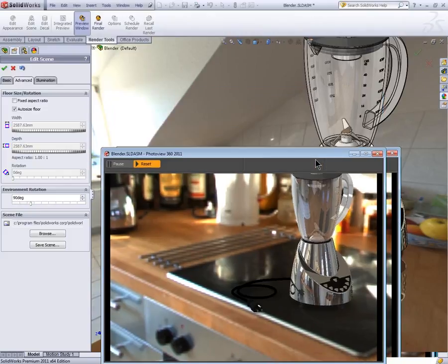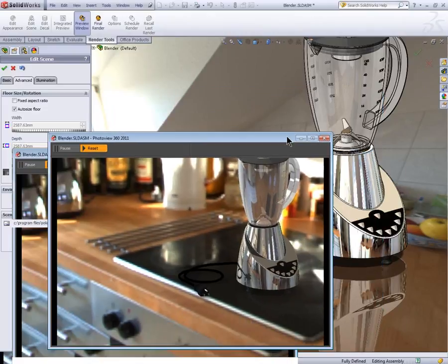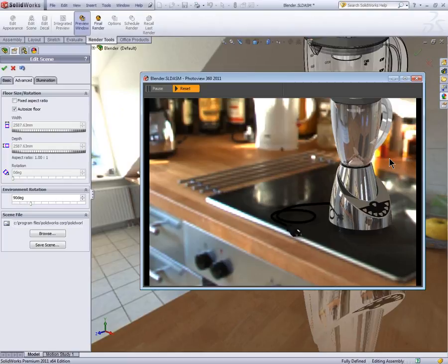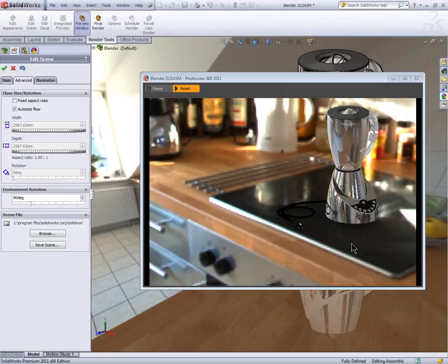Alright, so now it may not look right in the SOLIDWORKS environment, and again, this has a little bit to do with your PhotoView render size versus what you're actually seeing on the screen. So if you're doing like a 16:9 render size versus what you're physically viewing in SOLIDWORKS, it's going to throw that aspect ratio off a little bit. So that's why we're distorted. If you had your PhotoView settings set to use SOLIDWORKS view, then it would be more accurate.